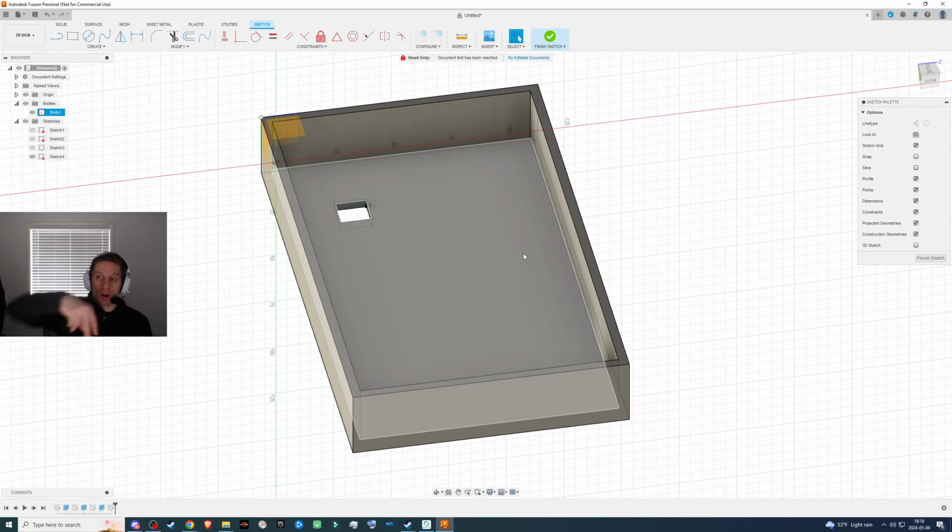The way a 3D printer works is it prints a layer and then it goes up and then it prints a layer and then it goes up and then it prints a layer. How much it goes up is a parameter of yours. You say, how much do I want it to go up? And this greatly affects print quality. So for real numbers, I plan on printing this at a print layer thickness of 0.2 millimeters. This is very common. I do things at 0.2 millimeters a lot.